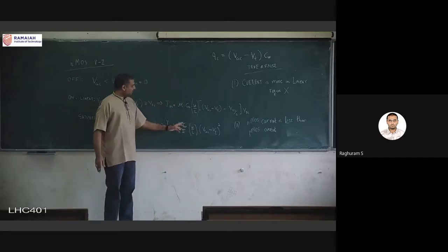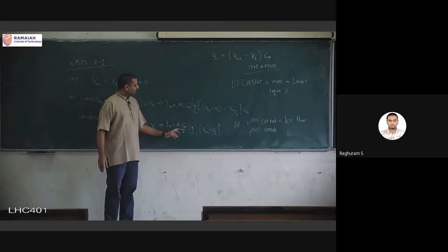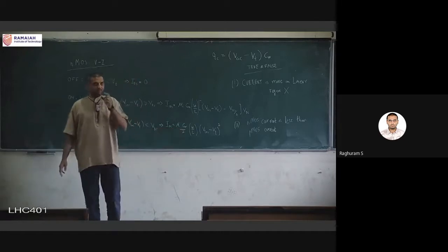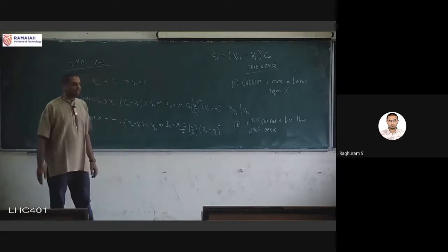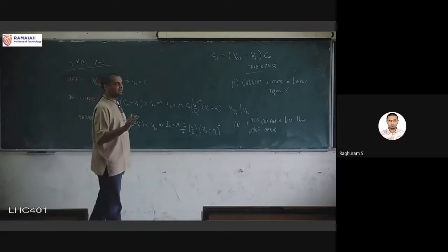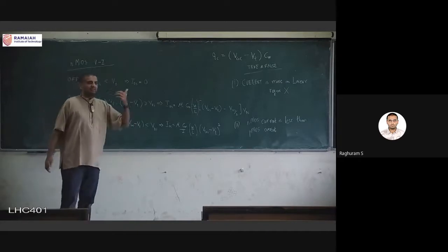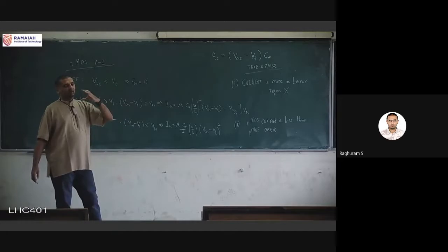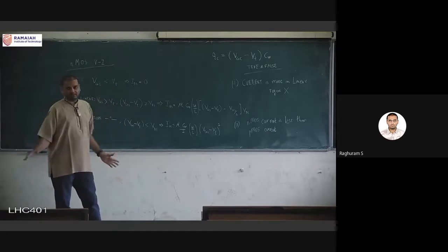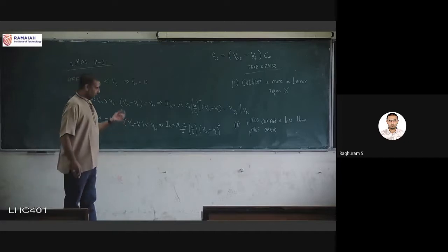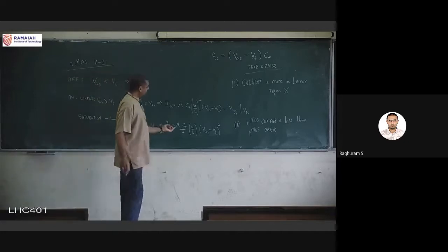Then we have mu C_OX by 2. Now mu and C_OX, we said they are material parameters, but here is the first difference between NMOS and PMOS. C oxide will be the same for both transistors, because C oxide, as we will see in the numericals, depends on the silicon and the thickness of the oxide region, and that will be the same because they're all made in the same technology. I can't make one transistor in 180 nanometer and another transistor in 90. It's just not possible. So the only thing that is remaining is this mu.